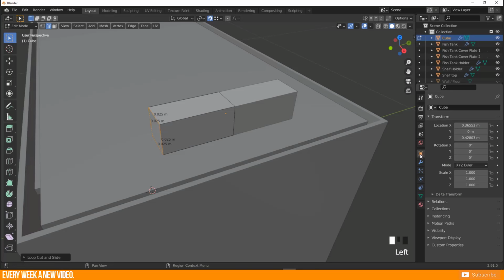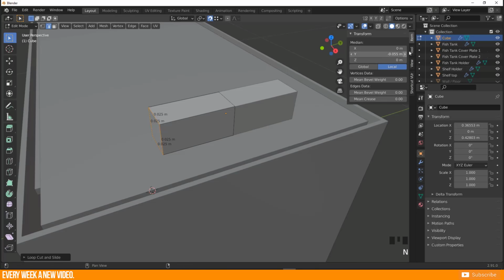And I can't do this sadly here because we have these transform values already here. We need to transform this edge loop to the epsilon direction, and you have to do this with the N panel. And when you open it here, then you have the exact position of this, and I want to just add the value plus 0.02.